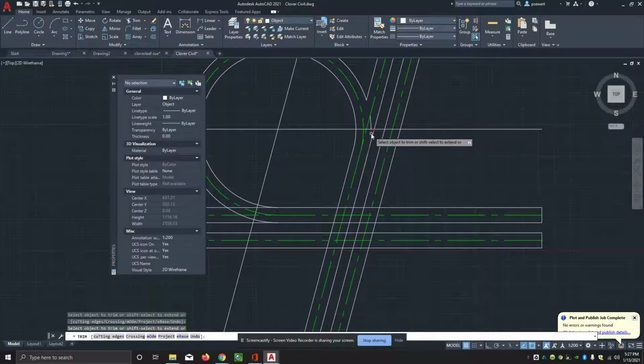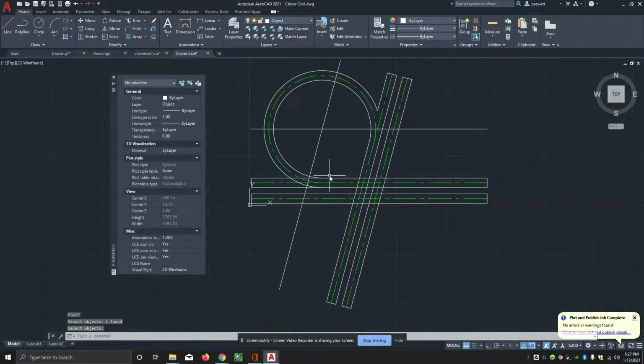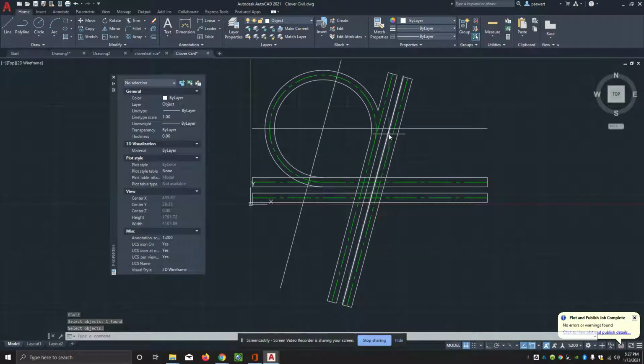That's an erase there. Yeah. I guess you could trim it twice just to get rid of it. Yeah, we got some erasing to do. But basically, yeah, so you're just cleaning that up. And you can do the same thing down here with an offset command. Do that 310 again. No, it's different. This one is a radius of 250. Oh, okay. I didn't see that.